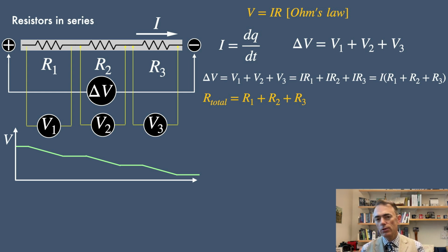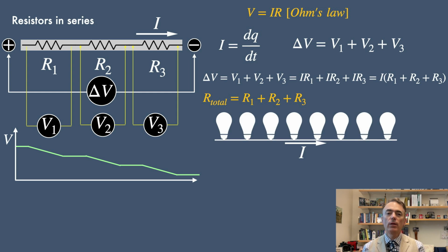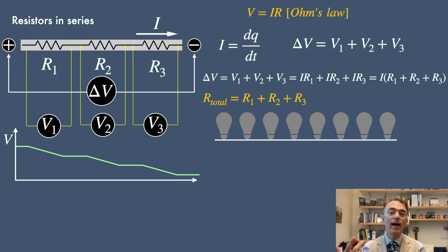There are some advantages of series circuits. They are simple to design and build. If more resistance is needed, resistors can be easily added in series. A disadvantage of these circuits is that if one component fails, the entire circuit is broken. For example, if a bulb burns out, the current is cut and all bulbs go out. The total resistance increases with each added resistor, reducing the overall current in the circuit.